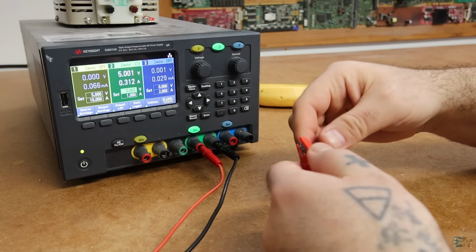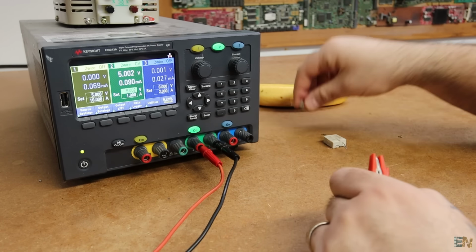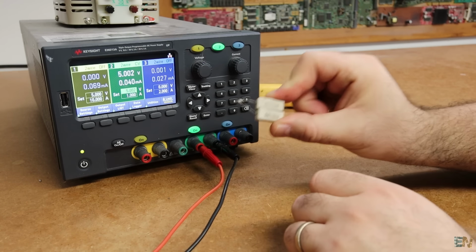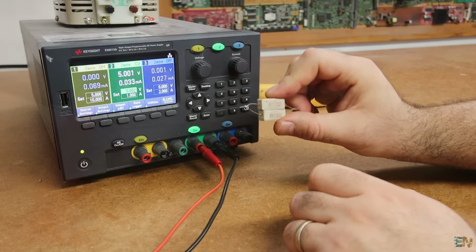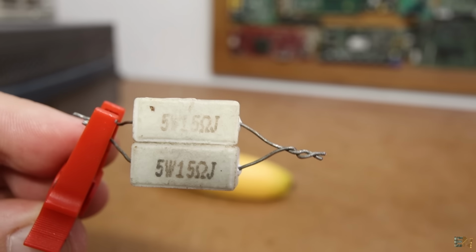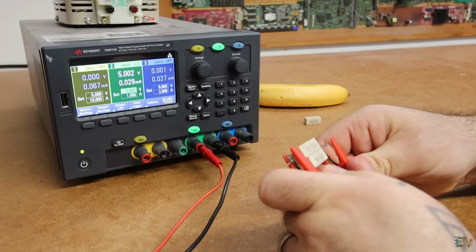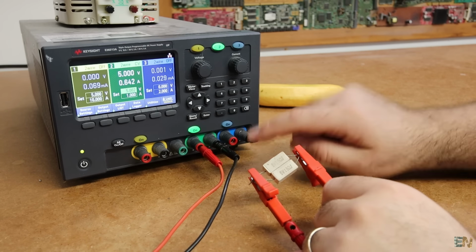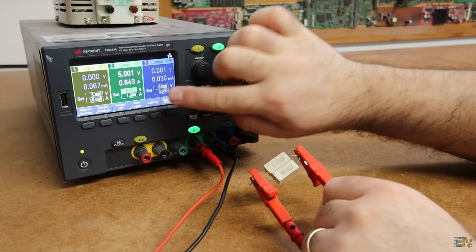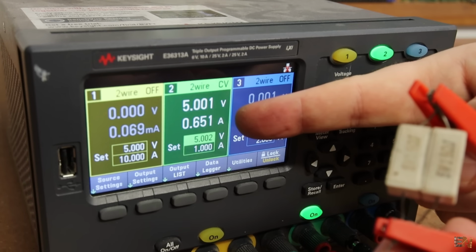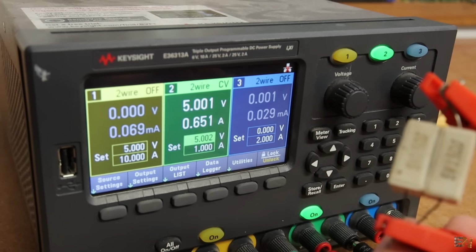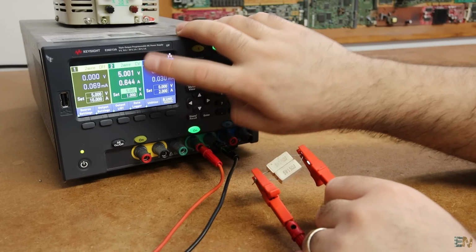Now if I decrease the resistance, so I increase the load, in this case I add 2 of these in parallel, so now the resistance is half of 15, so 7.5 more or less. As you can see, the current will be double. So instead of 300 milliamps, we have 600 milliamps. But since I haven't reached the maximum value yet, which in this case will be the maximum value of the solar panel, the output is still 5 volts.